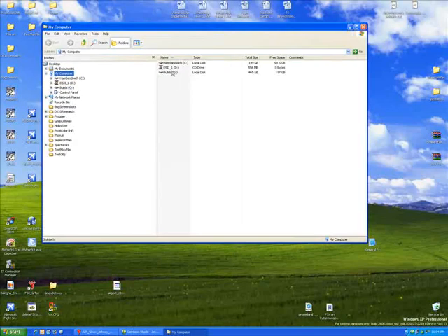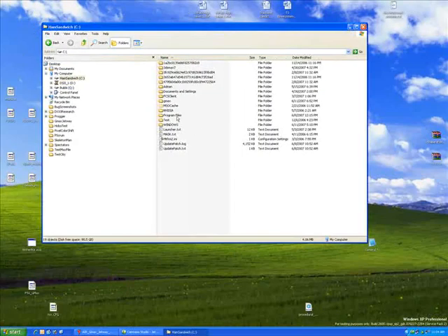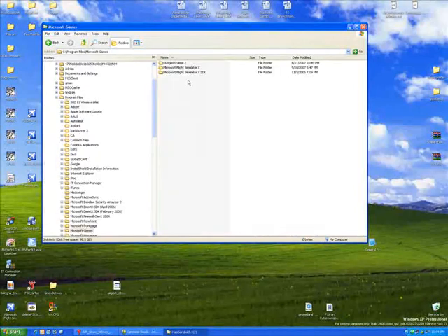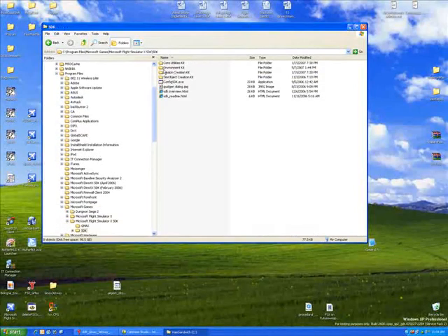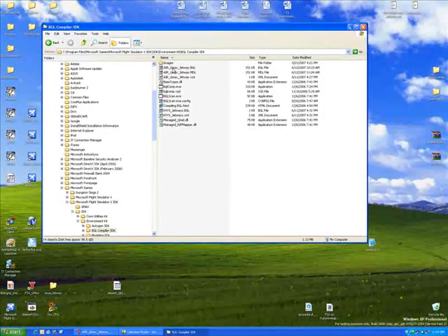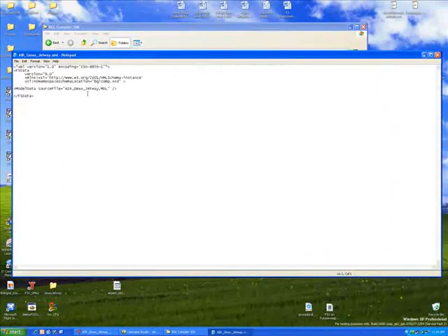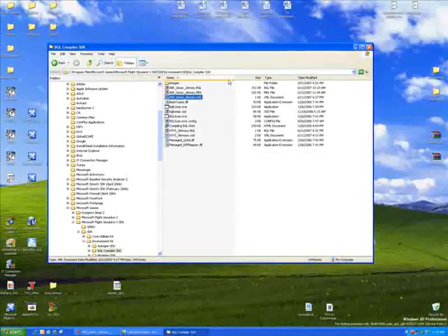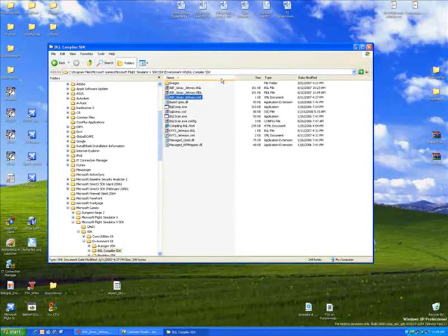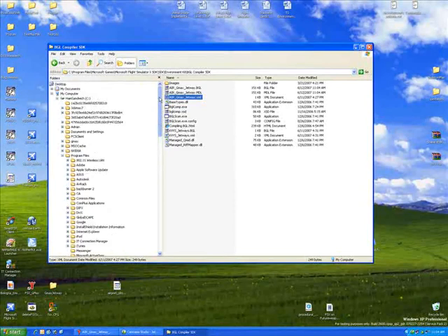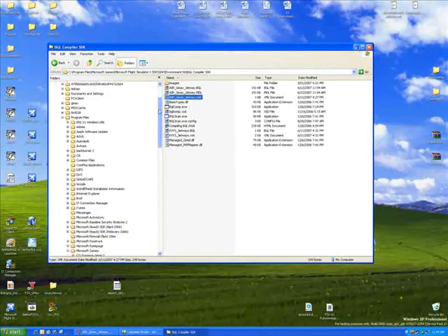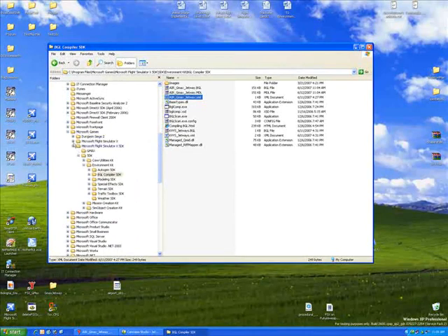Now if I go to the location of that, which happens to be in my SDK, in the BGL comp, you'll see I've made an XML file that just has the Jetway MDL, so I'm basically creating a BGL to reference. If you're creating an airport, you can reference that out of the BGL. I'll take that XML and run it through BGL comp, and it just updated the Jetway BGL, which contains the MDL file. And now I'm going to copy that into my add-on scenery.